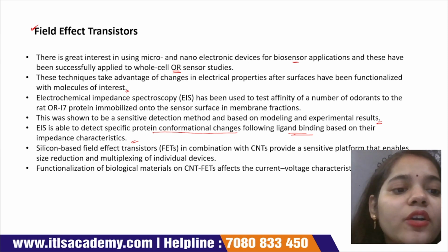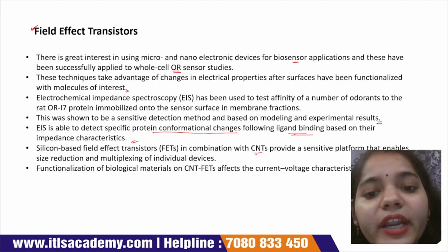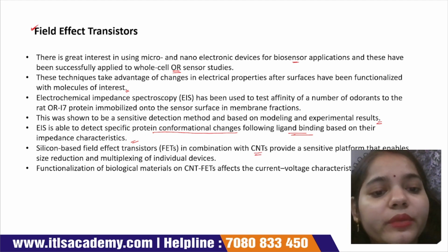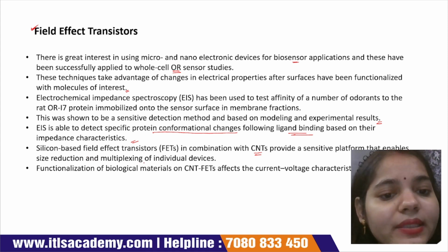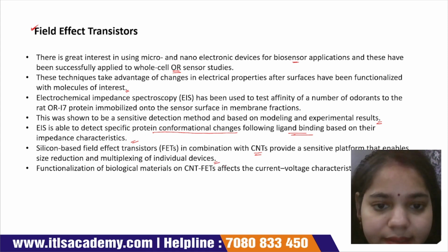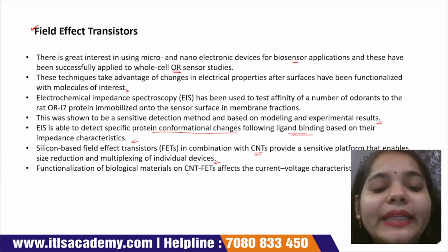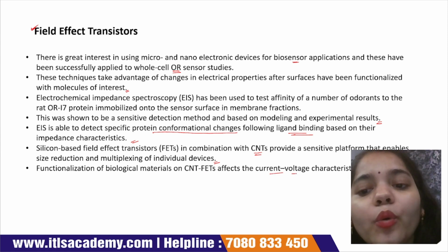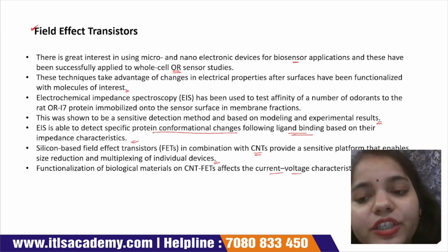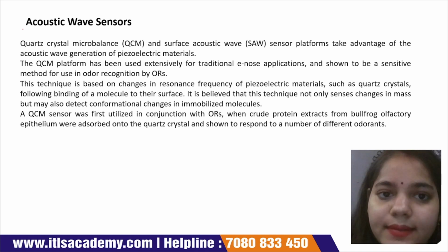Silicon based field effect transistors in combination with carbon nanotubes provide a sensitive platform that enables size reduction and multiplexing of individual devices. Functionalization of biological material onto the carbon nanotubes and field effect transistor affects the current voltage characterization of the carbon nanotube. Now we understand the acoustic wave sensor.